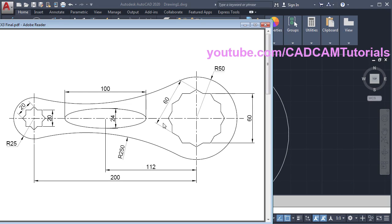Then next is to create this shape. Now in this shape there are two hexagons. First one is this one and other is this one. The size of both the polygon is 60, and again the gap is given between two opposite parallel lines. Therefore again we will use circumscribe method, and we will have to give radius of 30, that is half of this.